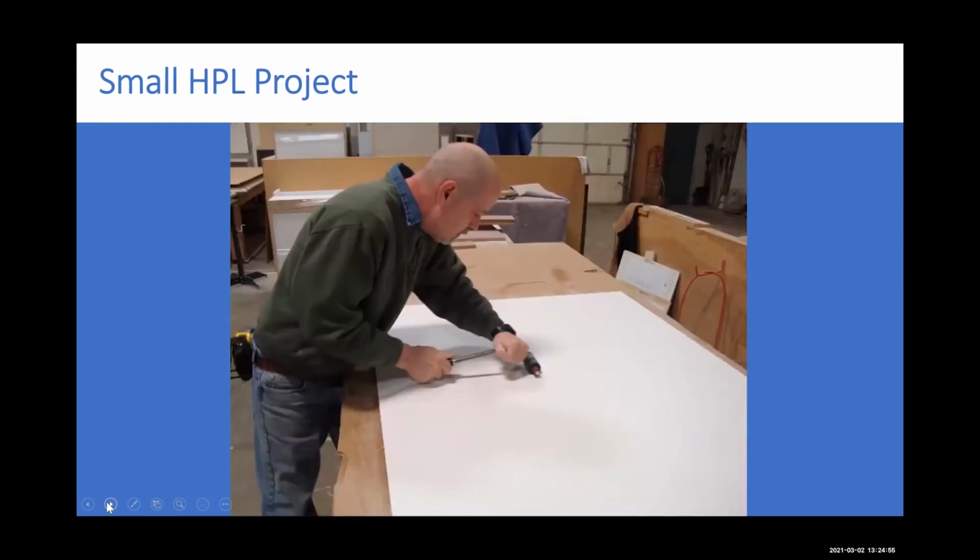He uses a tool called a J-roller, which assures the contact between the laminate and the substrate is made and adhesion is complete. A J-roller gives 40 pounds per square inch, giving the best bond. And the way he holds it distributes even pressure, removing all of the bubbles. On a warranty claim where only the edges are lifting, you might ask if sufficient contact adhesive was applied to the edges.